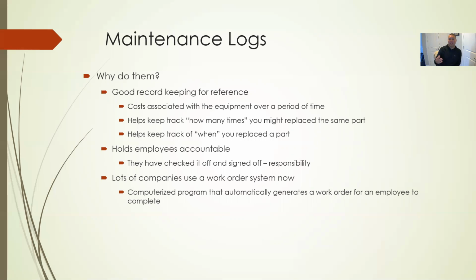Without keeping track of the maintenance logs and what you're doing on these pieces of equipment, it's hard to put that cost associated with the equipment. Okay, and it helps track of when you do it, right? So putting that down on a piece of paper, if we did it every 6 months, we replaced those wheel motors in 6 months time. Gee whiz, now all of a sudden I'm replacing a wheel motor every 6 months. That gets expensive.